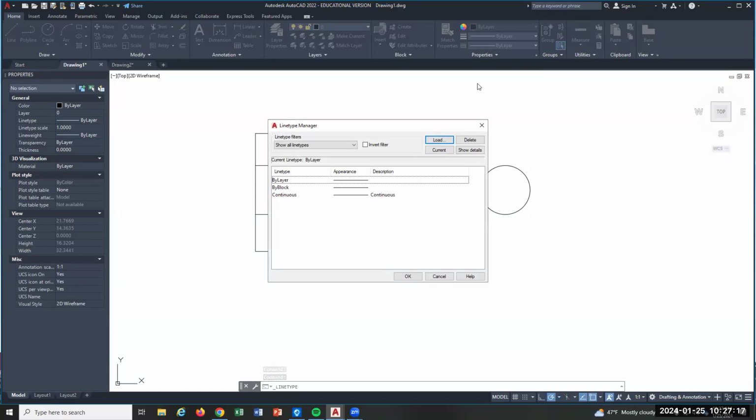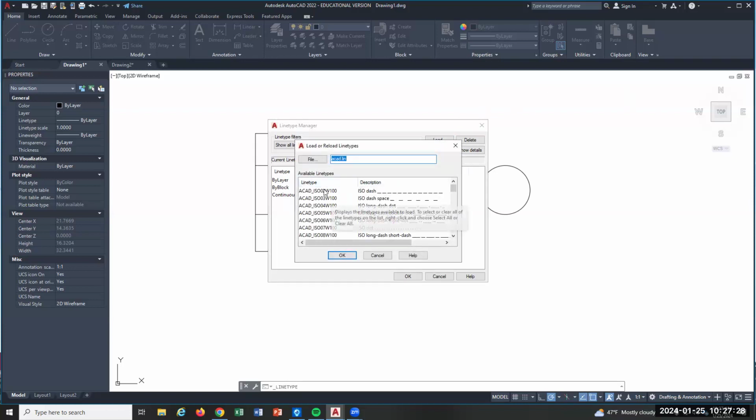Here's the line types available. Not very dramatic, but we can load line types. Notice how it's highlighted. Just trying to help you. Load it. The first sets are metric. I'll pass them up and I'll go down to the US sets, and then there is hidden. It's alphabetical. See it? Multiple types of that. So hidden, and then hidden 2, that's half. So see how it's smaller? And then hidden times 2, and that's bigger. I don't know what this little dialog box thing is. Go away. Oh, okay.